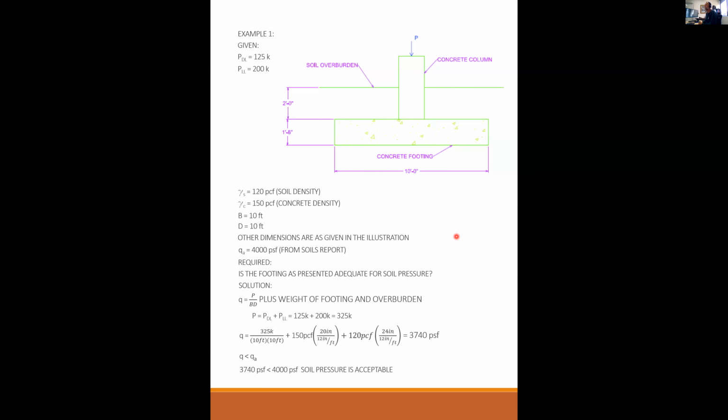And the church has been there, I don't know if anybody knows better than I, but at least 300 years, I'm thinking. And luckily, they did not have differential settlement. Just the whole building went down evenly, nice and even together. So the building's fine. It is just 6 to 8 feet lower than it was when they built it. They had to dig themselves a new entryway and put steps in there so you can walk down to the front door. Anyway, that's my detour on soil settlement.